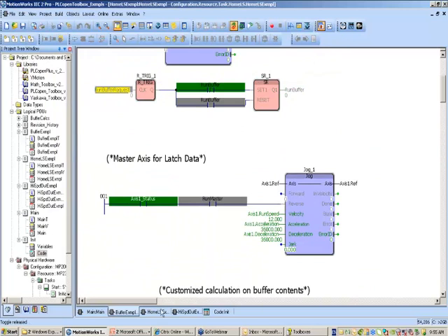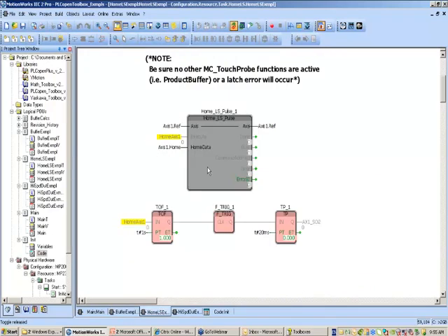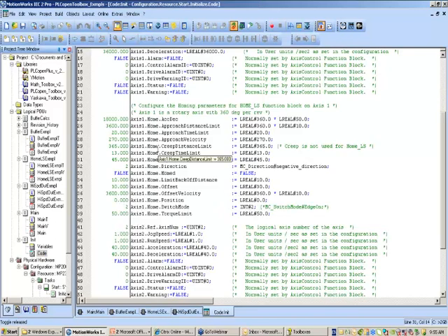So the rest of the homing setups can be set anywhere. They can be set in the program. I've chosen to set them here in my initialize code. So just for axis 1, .home is where all the homing elements are placed within the axis structure. And you just go through and set these. This axis is actually a 0 to 360 degree rotary axis. So I just set my XL to 50 revs a second, approach at 10 revs a second, and so on. And at the end, I'm going to set a position of 0.